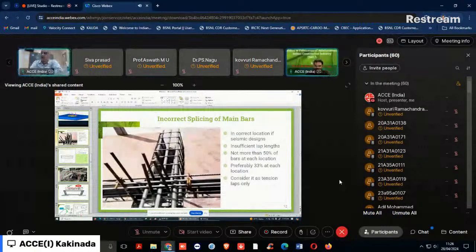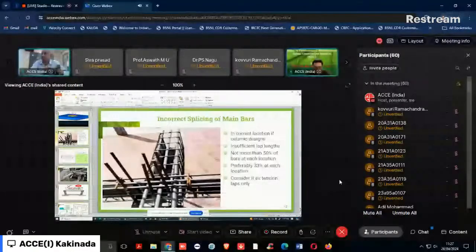And after that, we'll see the very important requirement of the rebar detailing of the column bars. Generally, as per the Indian practice of the steel industry, 39 to 40 feet is the length of the bar that is available. Definitely, we have to lap the bars at desired locations, and the selection of the lapping location is very important, besides the lap length and the number of bars to be lapped. These are the three important parameters.